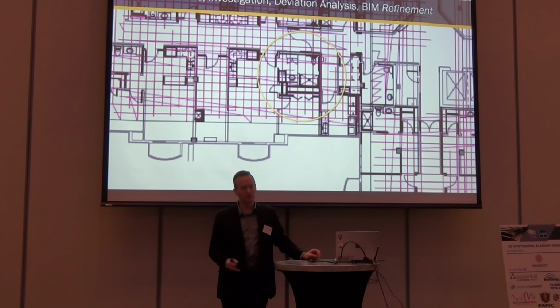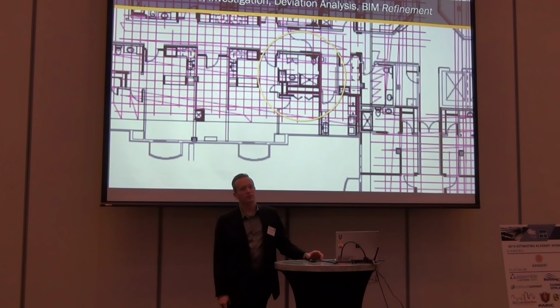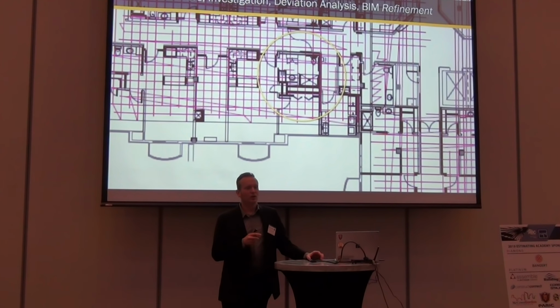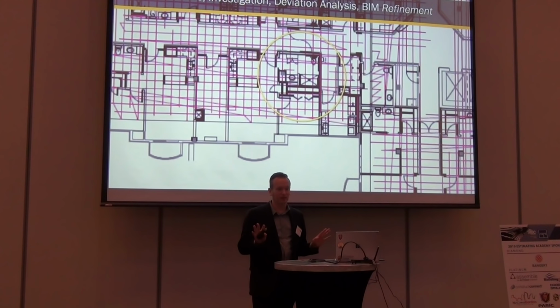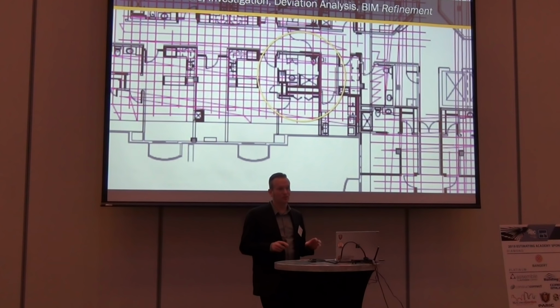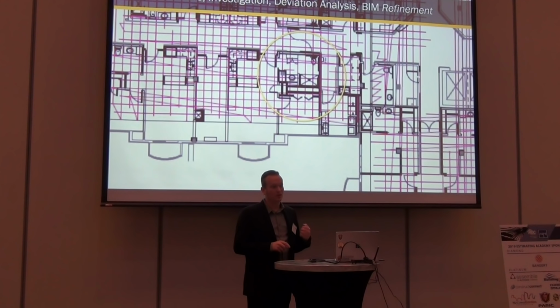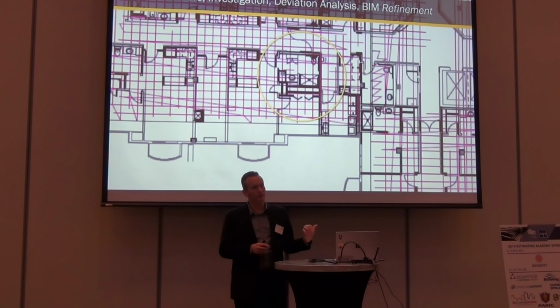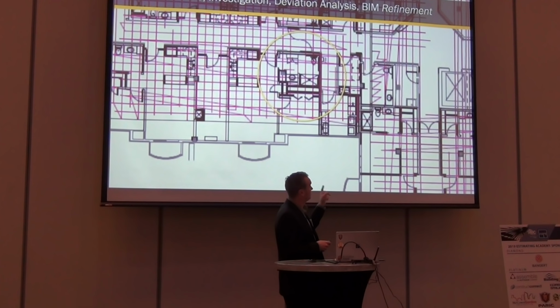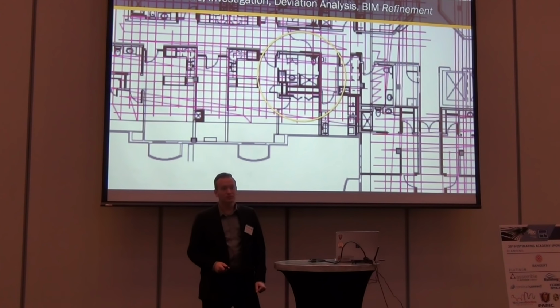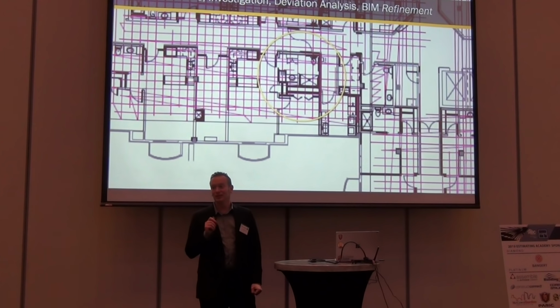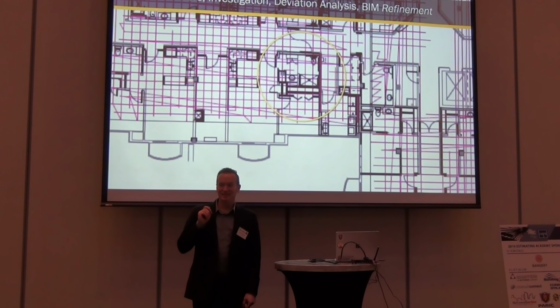So we went to start repositioning this building and putting in new demising walls and new wet walls and things like that. In some places, we were right in the middle. We were clear we were going to hit a tendon. Other places, not so much. In historic renovation projects, oftentimes you have to maintain historic corridors and things like that, so moving them is not effective. When we dug into this and realized how far we were going to have to go, the scans became critical to the success of that project. No different than this example here. All these magenta lines represent post-tension slab cables. Have you ever done a repositioning on a PT slab? It's a great time.